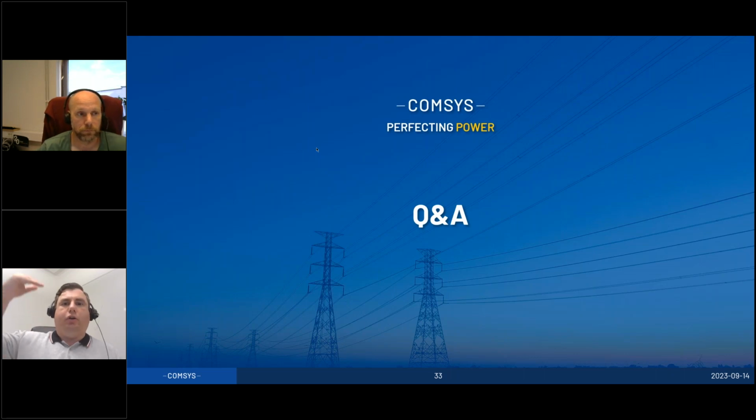Excellent. So you make an auto tune, then you get the settings, and then you can adjust that a little bit. Correct. I got one quite interesting idea from a customer. They were asking, if we only have the IEEE 519, but we are doing both the voltage and the current, can't we just set up the short circuit ratio of 2000 and run the IEEE auto tuning and get a nice result for 8% voltage overall and 5% single order harmonic?